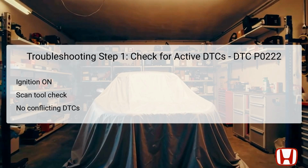P0123, or P0223. If any of these codes are present, they need to be addressed before proceeding to troubleshoot DTC P0222, because conflicting codes can prevent accurate diagnosis and communication with the PCM. A clear understanding of the active codes assists in narrowing down the focus of the diagnostic process, ensuring that the technician addresses the most pertinent issues first.